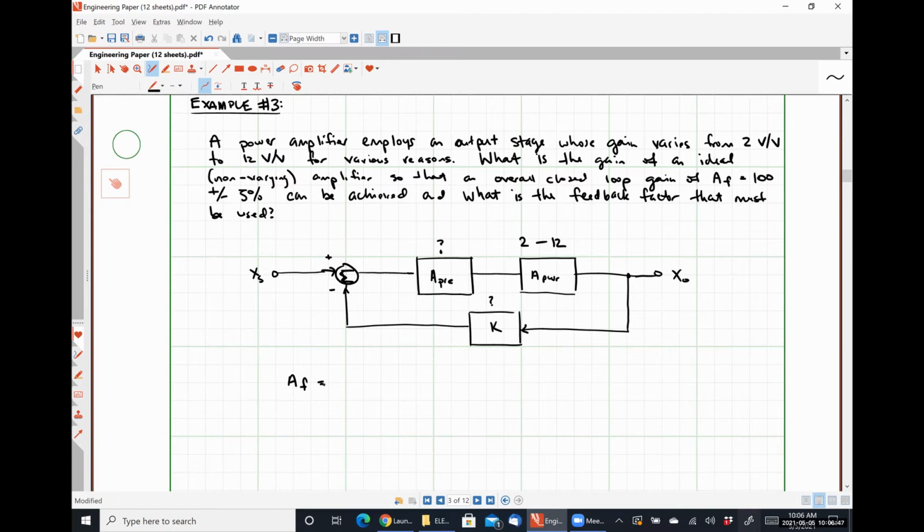How does this differ from our generalized case that we were looking at the beginning of class on Monday? So we're not adding them together, we're multiplying them together, right? It's 2 amplification stages cascaded together, which means we multiply the gains, just like when we were cascading op amps together, stuff like that, okay?